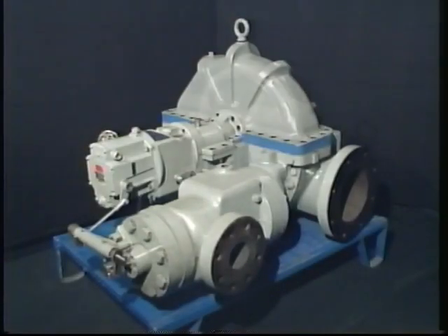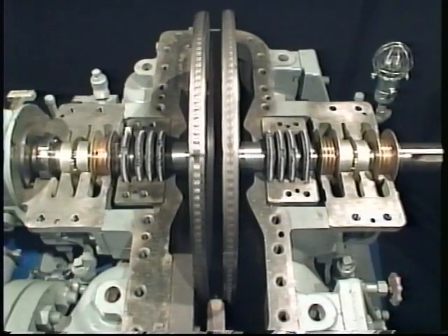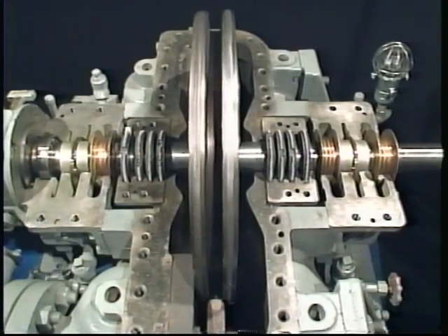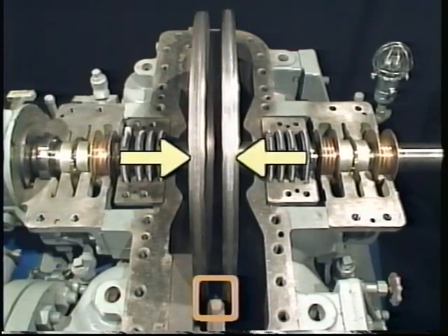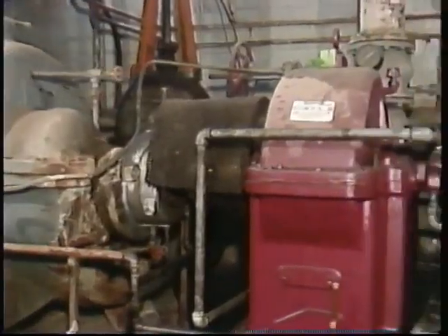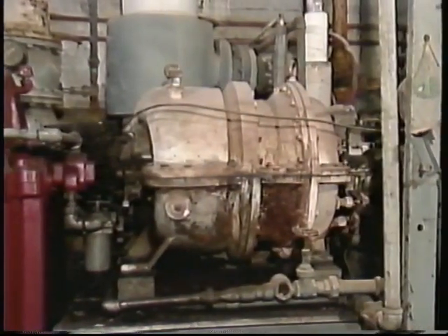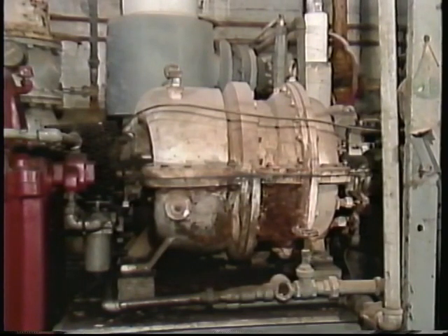The arrangement of blading we just saw is typically referred to as a single-stage turbine. Like the example you see here, single-stage simply means that a series of fixed blades is used together with one or two sets of moving blades. In this program, we'll be focusing on turbines similar to this one. There are other turbines that are called multi-stage turbines. In these turbines, a stage refers to one set of fixed plus one set of moving blades.